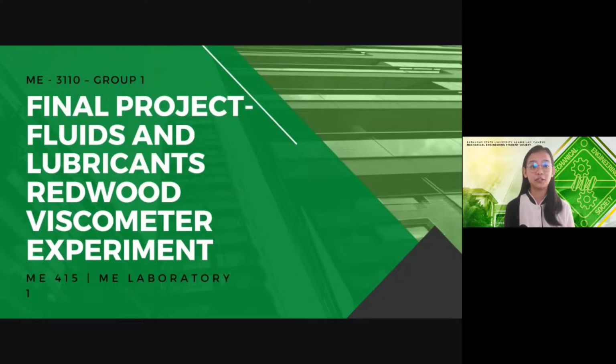Viscosity is a fluid flow property and is one of the most important properties of a lubricating oil. It is defined as the measure of fluid's resistance to flow, or what we call the internal friction to shearing stresses. We have two main types of viscosity, the dynamic or absolute viscosity and the kinematic viscosity. The former measures the ratio of the shear stress to the shear rate of fluid, while the latter measures the ratio of the dynamic viscosity to the density.